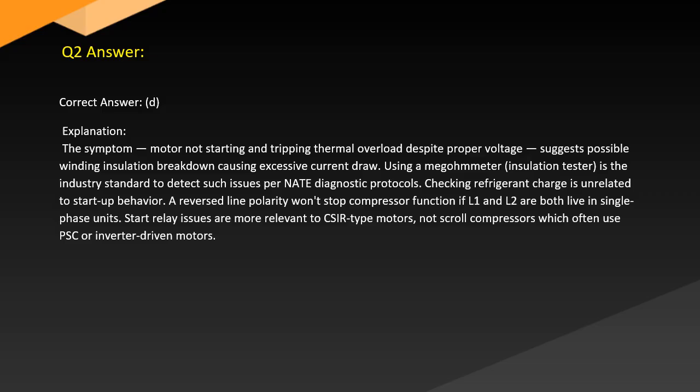Checking refrigerant charge is unrelated to startup behavior. Reversed line polarity won't stop compressor function if both legs are live in single-phase units. Start relay issues are more relevant to other motor types, not scroll compressors, which often use PSC or inverter-driven motors.